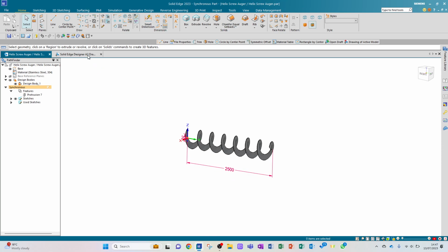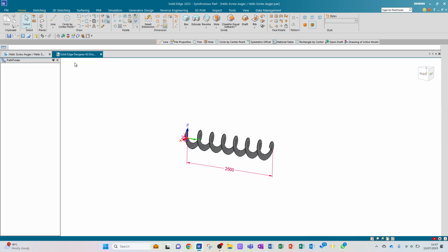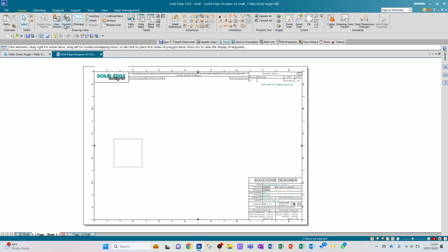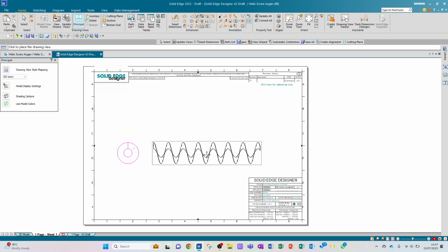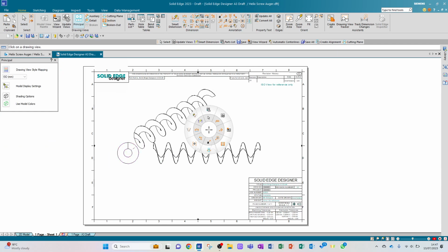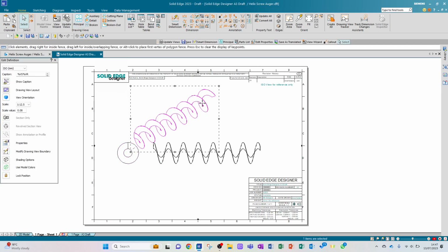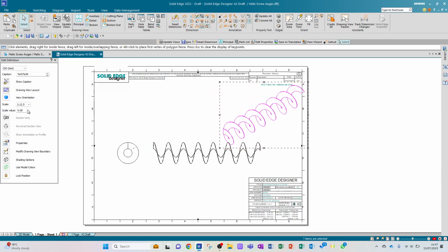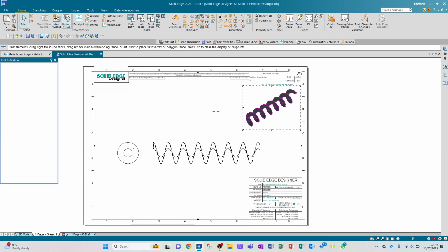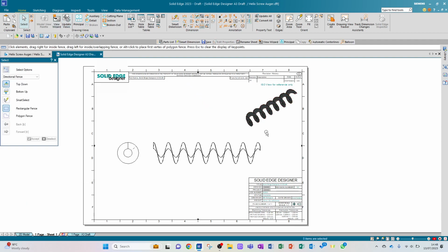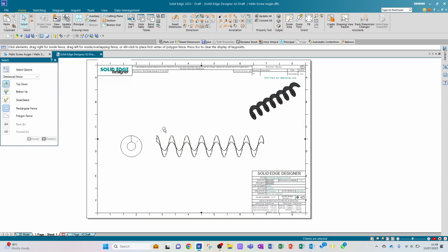I've already created a draft file off the part file earlier on. So if we just click on here, I'll update views and go principal. If we drag that over here, we can get our views. ISO view, which is for reference only. Just change the scale on this. Put that up in this corner, and we will shade with edges. I think it always looks nice when it's the ISO views coloured in when it's on a PDF.